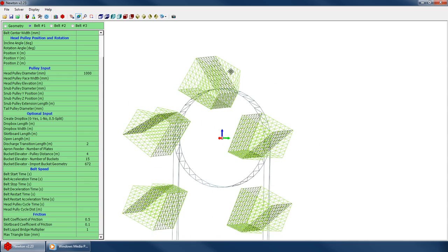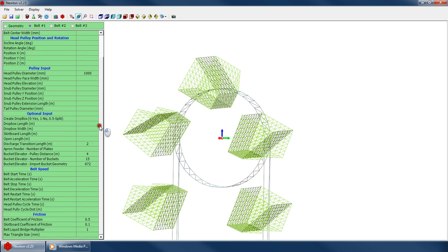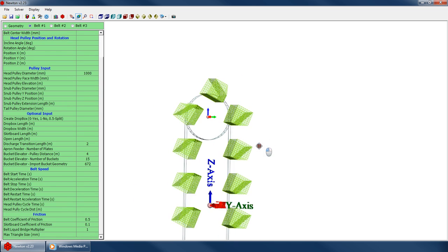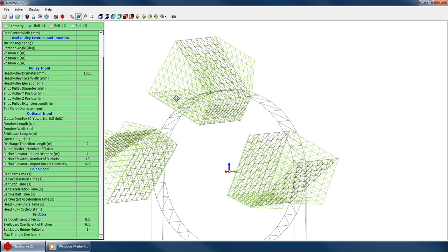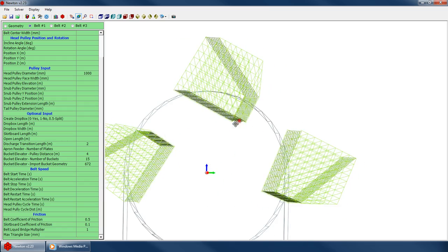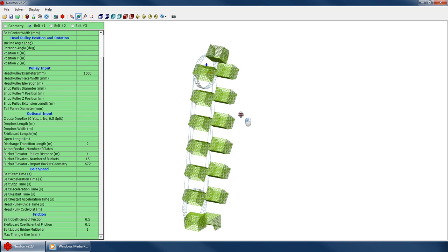And currently, you cannot simply import a bucket and mesh it up in Newton, like using our equalized triangles. That doesn't apply to any of this internal geometry. So it's best if you mesh up the geometry externally, mesh up your bucket externally. And that also gives you the opportunity, at the same time as you're meshing it up, to remove any bucket thickness or extra surfaces or extra material that you just don't need in the bucket. Because we want the simulation to run as fast as possible.